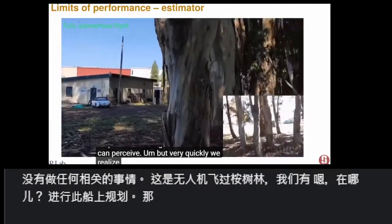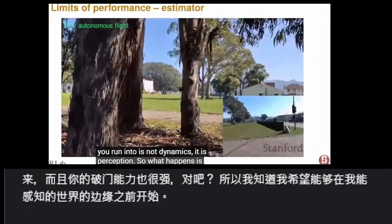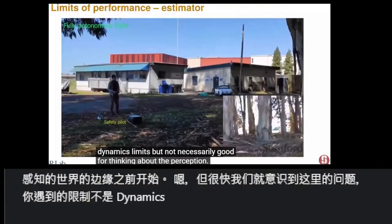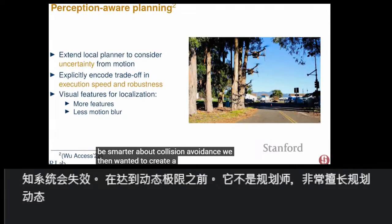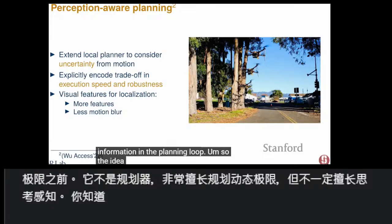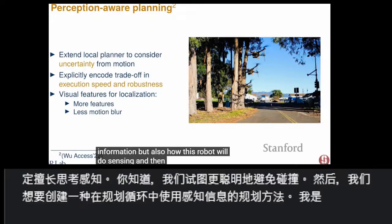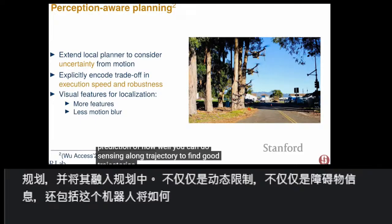But very quickly we realized that the limit you run into is not dynamics, it is perception. What happens is the perception system will fail before you hit the dynamics limits. And our planner is very good at planning up to the dynamics limits, but not necessarily good for thinking about the perception. So in trying to be smarter about collision avoidance, we wanted to create a planning approach that uses perception information in the planning loop. The idea is when I'm doing motion planning, incorporate in the planning not just dynamics limits, not just obstacle information, but also how this robot will do sensing, and then try to use prediction of how well you can do sensing along a trajectory to find good trajectories.